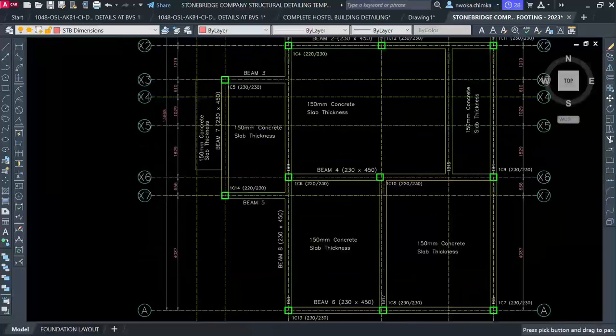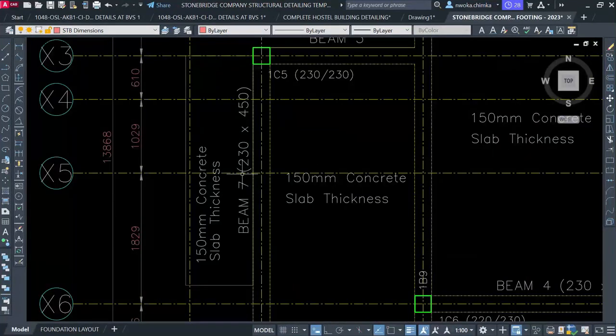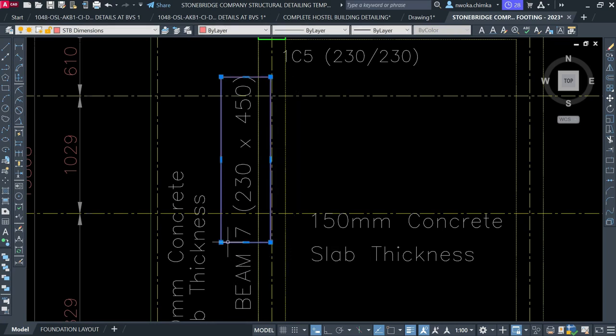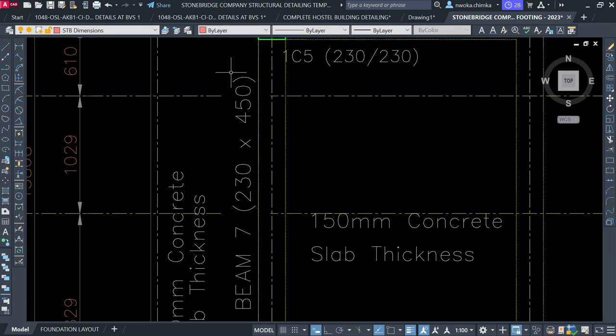If you don't want this line crossing the text, you can just draw a rectangle over this place, over a certain level here. Use your eye gauge to place it somewhere here, then click on the rectangle and trim. Trim off this stuff here and this stuff here also, then escape, and remove this rectangle line that is here. Okay, that's fine. You can now see it, right?